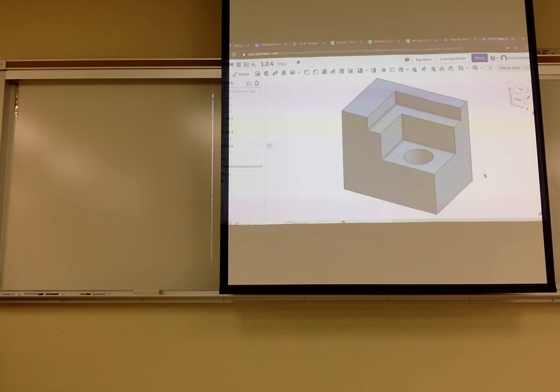It's in this corner. Well, how big is it? Well, 2 inches by 2.5 inches. So I'm going to write this one is 2.5. This one is 2. That's the shape that I want. Now I extrude it, but I don't want it to add material, right? Remove. And it'll typically flip the direction for you.